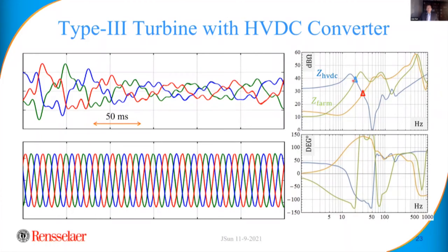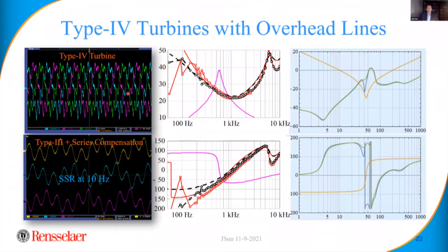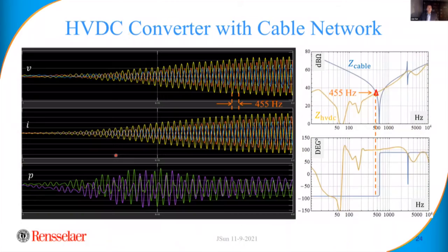And that intersects with the capacitive impedance of the HVDC converter at that frequency, right? So you form a perfect series resonance, and the phase difference will determine whether that resonance is stable or unstable, right? So frequency domain analysis is supported by either time domain simulation or measurements in the lab. That's how we perform the analysis, what we call case studies.